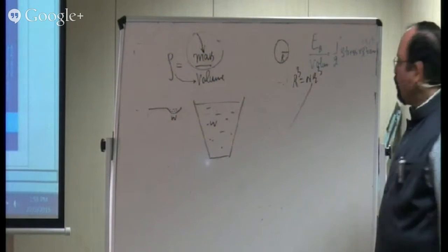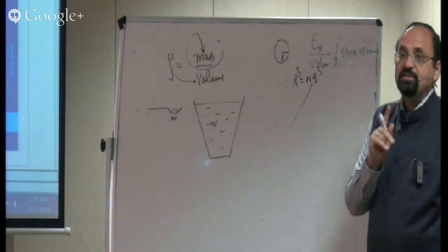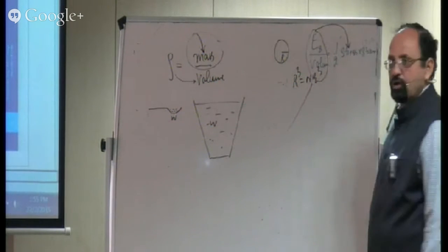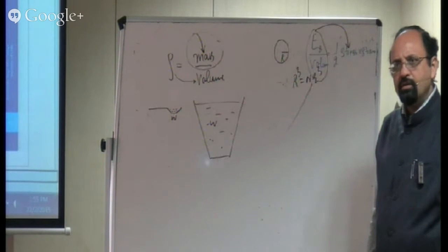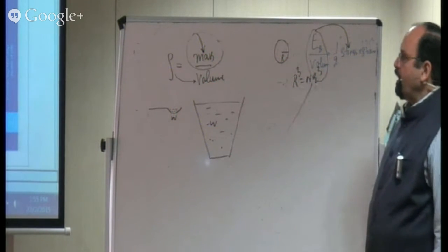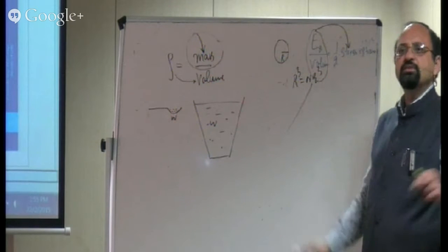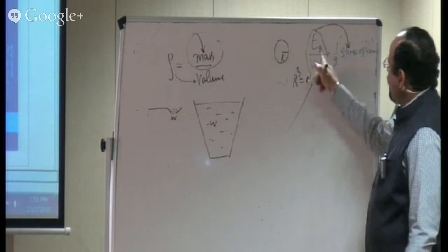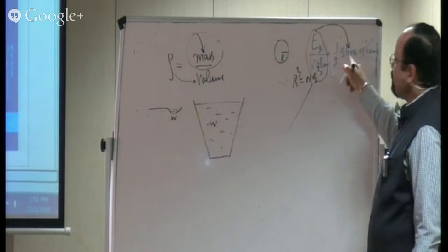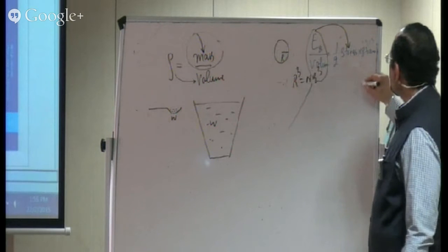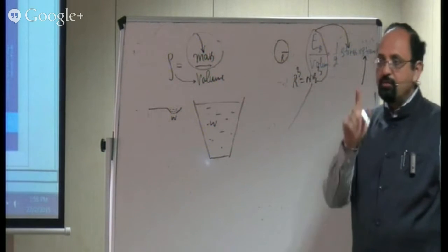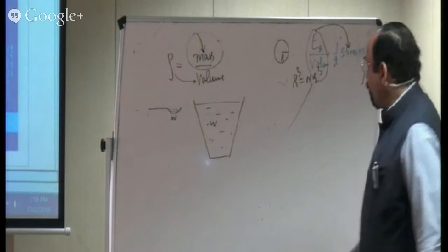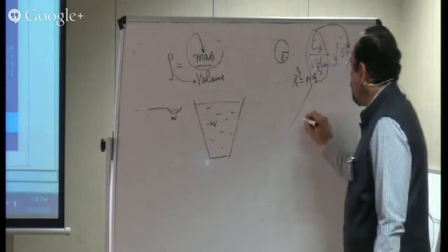Looking at this relation, you may land up with a wrong answer. Energy per unit volume directly proportional to stress means a linear relation. Your answer could be A or D, and both are not the answer. What wrong has happened? When I relate energy per unit volume with stress, I must not forget there is a term strain also involved in it. Before I go for it, I do a small change in my formula.